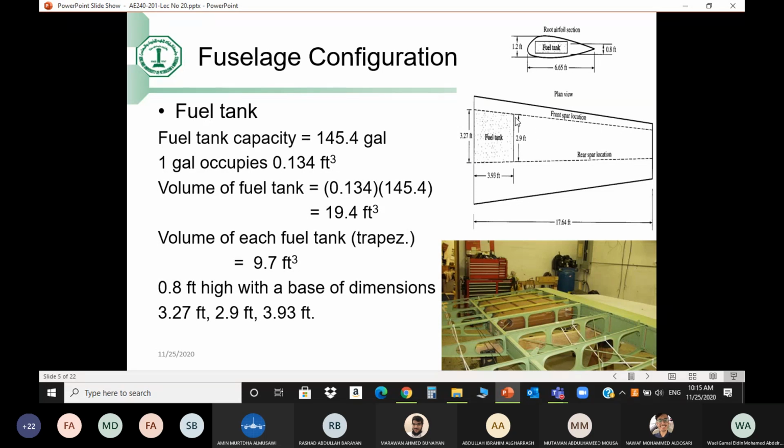Here I know that the distance will be that much. It will decrease until it becomes the distance between 1/4 and maybe 60 or 70% of the chord. So I know it will reduce down. I know that the height is constrained by the airfoil. If you were with us from the beginning, I showed you one way to get airfoil information, one library. Probably you all know that you can get the coordinates of the airfoil, so you know what's the height inside the airfoil. So if you draw the airfoil for this example that we had,